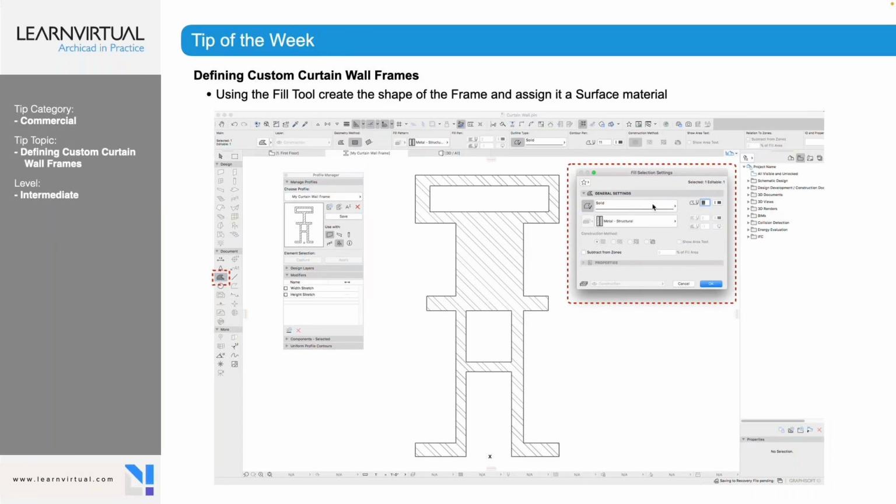So in this case, we're going to select metal structural as our fill pattern. We're going to select that we want to have a solid line around that fill pattern, and we want it to be a pen of 1 or whatever it is that you want to select for that. And as you can see, once we create that shape, it's going to have lines through it based upon the fill pattern that is selected for that particular metal structural frame that was created by Archicad.